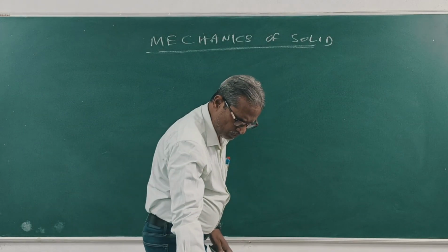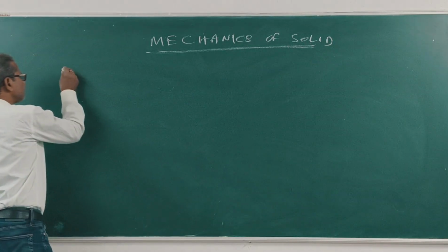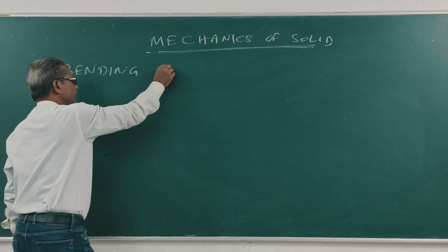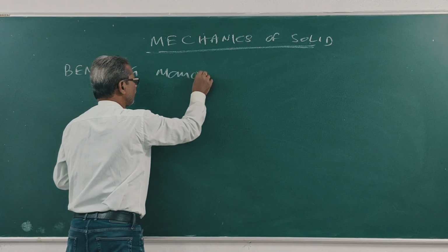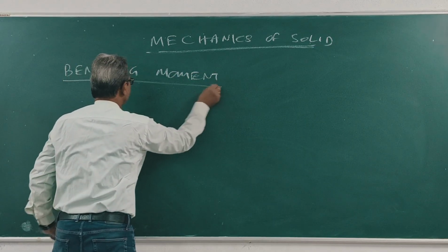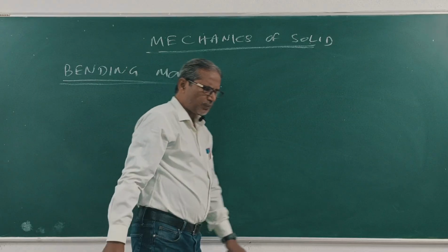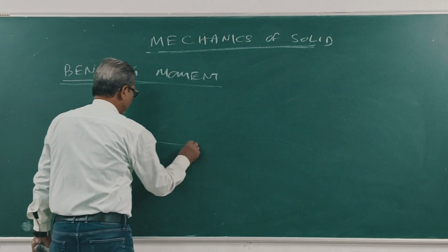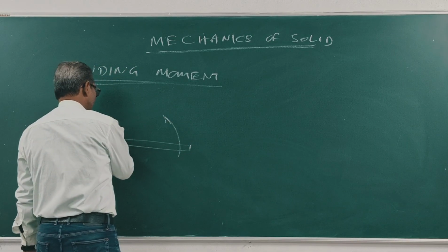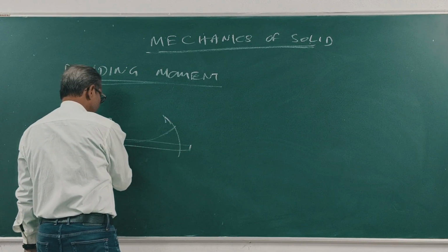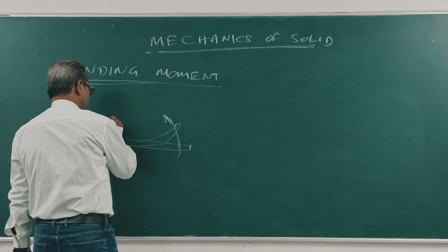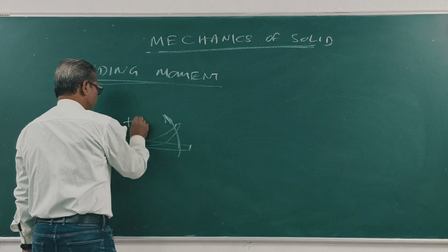Sign convention for bending moment. Clear? Suppose this is a beam, the force is applied and the beam bends like this, with concavity at the top. This is positive.